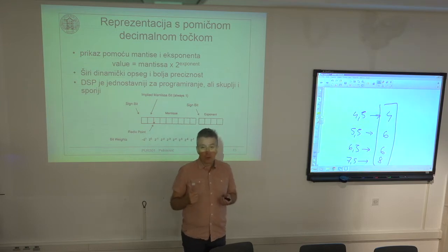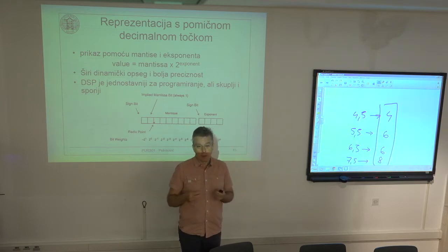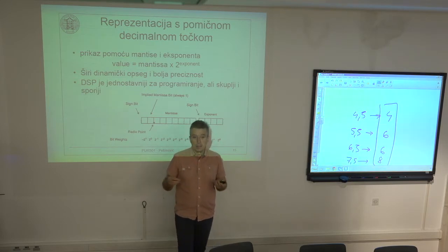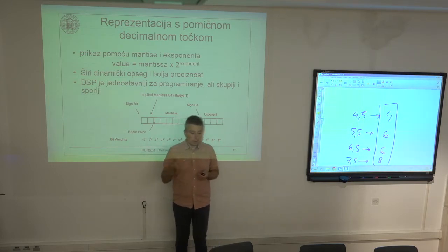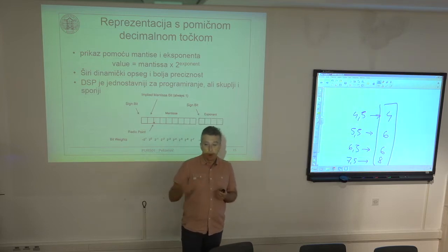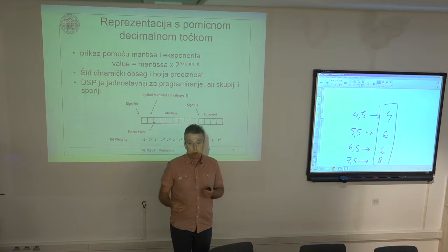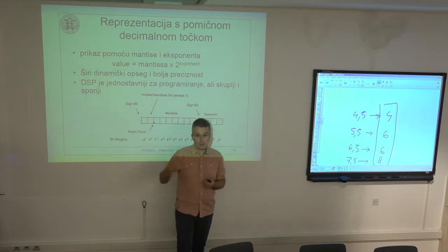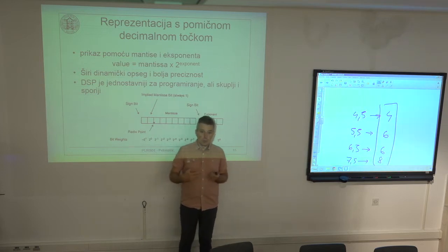It is proportional to the number of transistors changing state. If you have a larger number of gates necessary to implement these execution units, you have proportionally higher power consumption, because to compute this floating point value, a much larger number of gates must change state for each computational cycle.